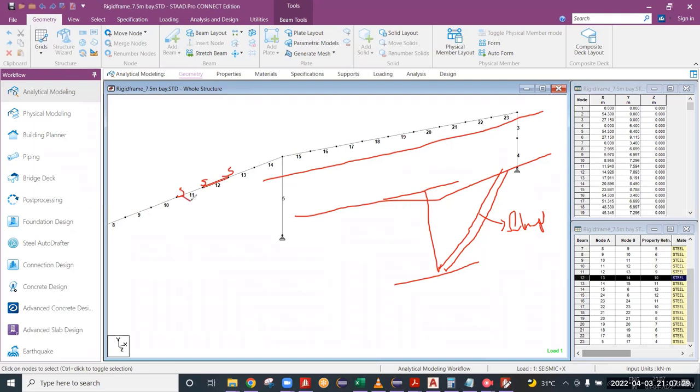If he provides one flange bracing to the rafter for this purlin, he will not provide it to the next one, and he will provide alternate ones. But this flange bracing is required everywhere, sir? Not necessary. Flange bracing is just to reduce the unsupported length of the bottom flange and web.